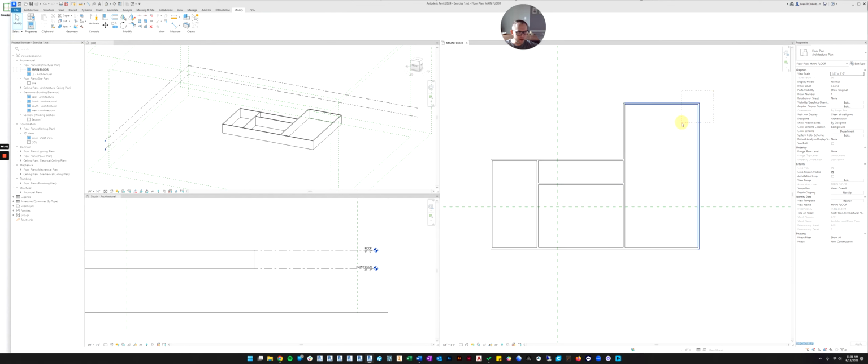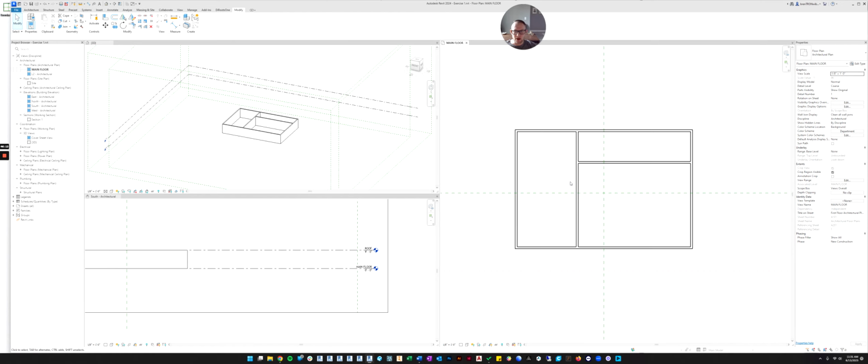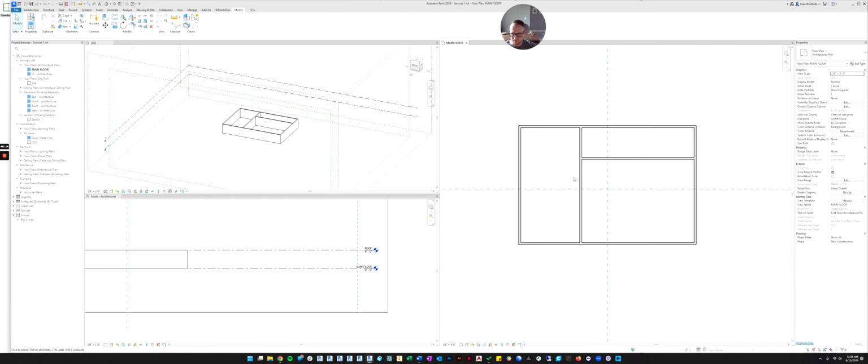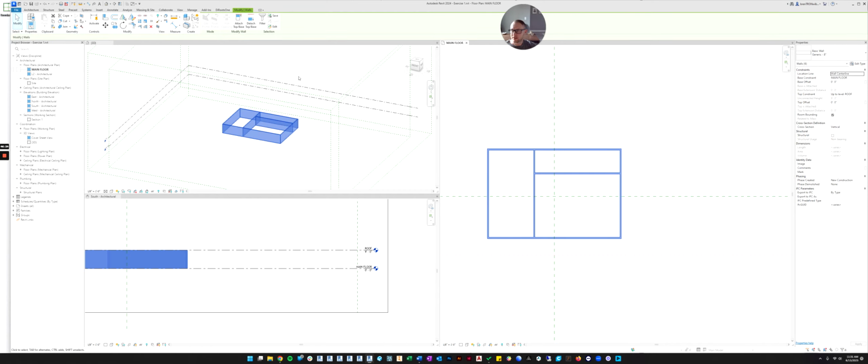All right, so let's go back to our original house. Let's delete that. Let's use the trim command to get those corners back to the way they were. And here we are back to our house. There's other modify elements that we will learn over time, like the mirror command. So for example, if I wanted this whole house flipped, I can go up here to the mirror command,